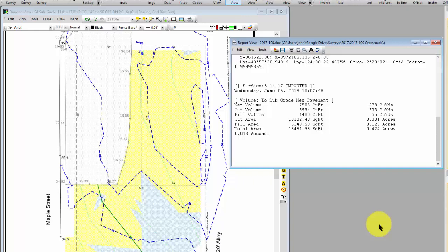Now I can change the design a little bit. I can raise that east end and waste some material doing that. And maybe I can get it down to 150 cubic yards. Okay, so 15 dump trucks. Now the church has another project where they might be able to use that sand, so I'm going to see if we can just keep that on site and ask Gary to do a little more cat work for the project. But this is all I wanted this for.